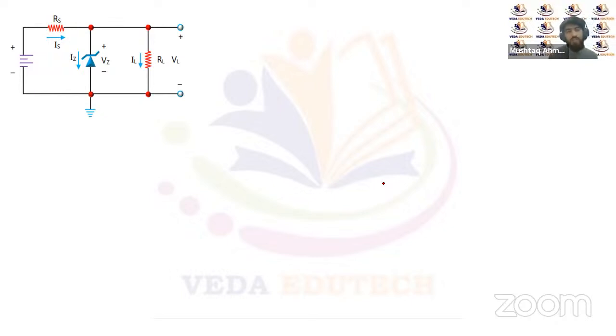We know that there is a specific, fixed breakdown voltage for every Zener diode, so the output voltage of the Zener diode will be fixed in the reverse bias condition. That's the reason we use the Zener diode as a voltage regulator in circuits.